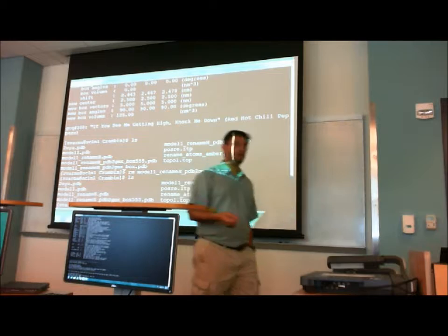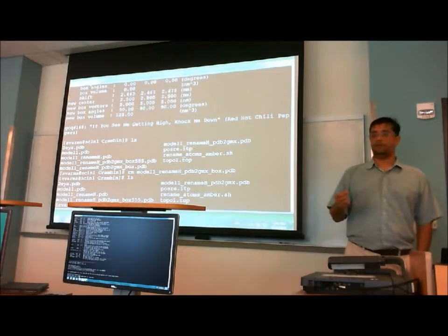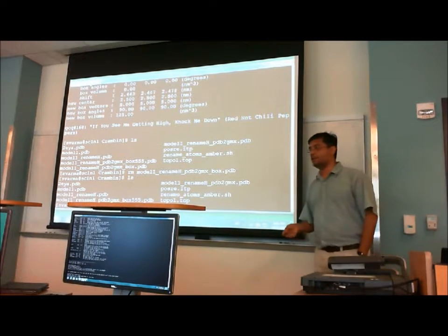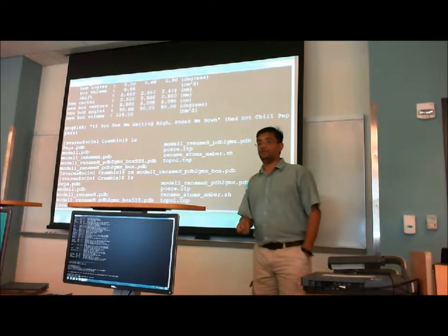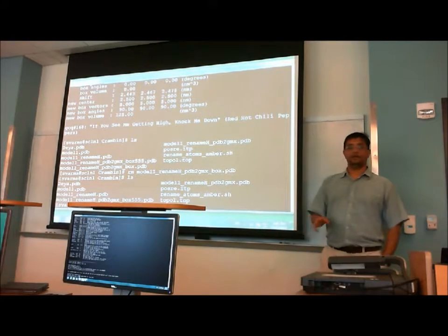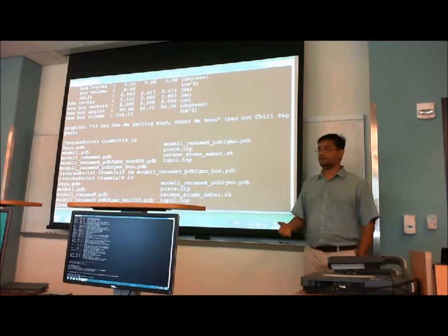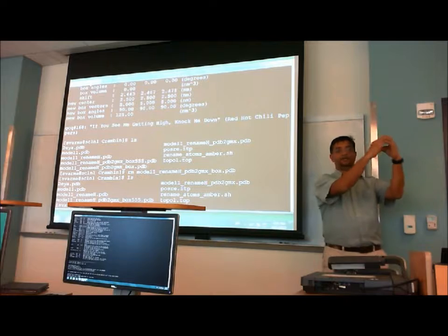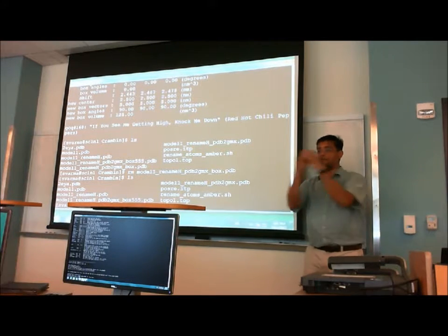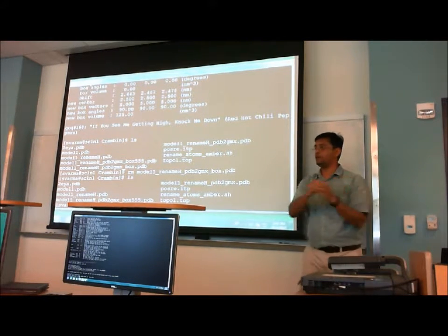Okay? So the code we're going to use for that is GenBox. So GenBox you can use for adding water. GenBox also requires inputs. It needs to know what the name of the input file is. So it's not -F in this case, it's -CP.